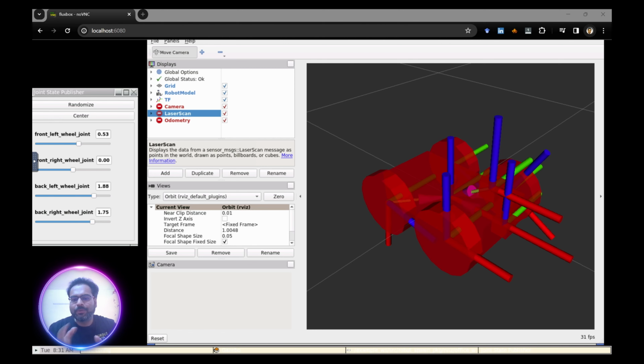But I hope with this lecture you get a basic understanding of what a URDF is, and if you want to customize this robot. For example, a simple customization could be a laser scanner, one in the front and one in the back, because right now a laser scanner at best would have a 270-degree sensing radius. We can add a sensing radius in front of the sensor so you know what that looks like. We'll do it next time when we start seeing the sensor feedback.